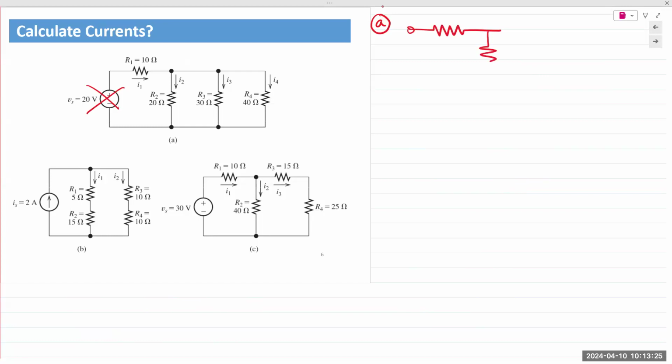redraw the circuit, and calculate Req, again, from the perspective of the source. So what do we see? When you want to find Req, we go to the farthest end and move towards the terminals of measurement, reducing the circuit step by step, one at a time.